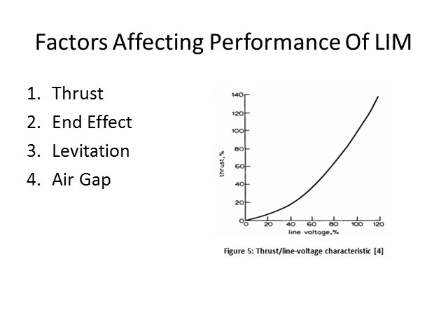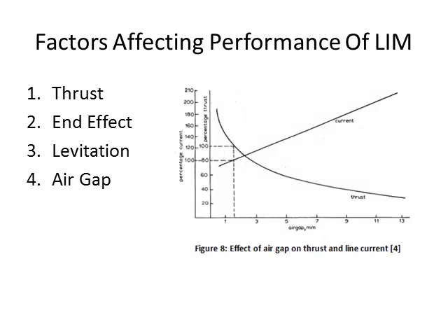The fourth factor is an air gap between the primary and secondary. A large air gap can serve to reduce the efficiency of the motor, since it decreases the force produced for a given power input. A larger air gap also increases the inductance of the motor, which means that we have to spend more on purchasing and installing the necessary capacitors.